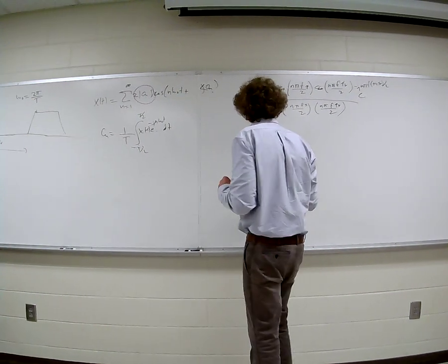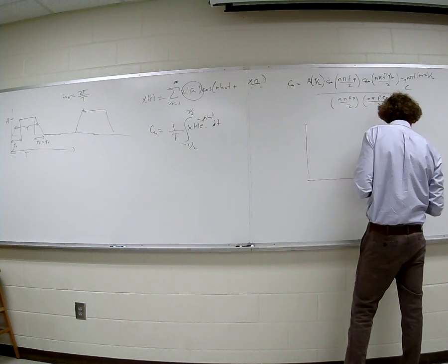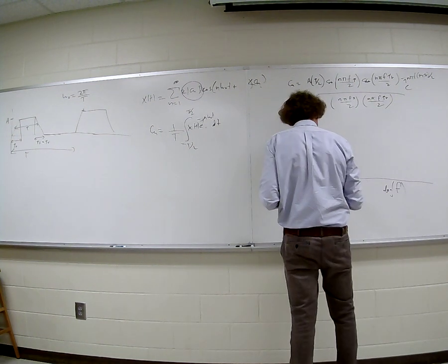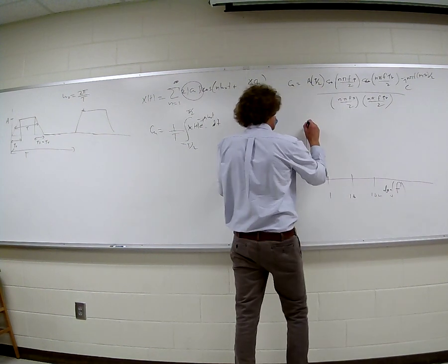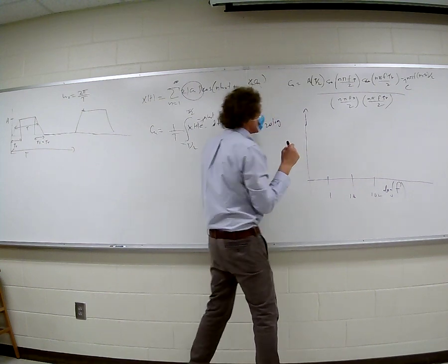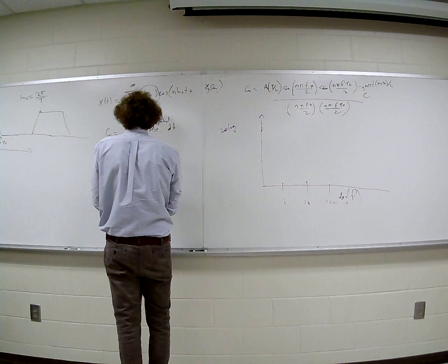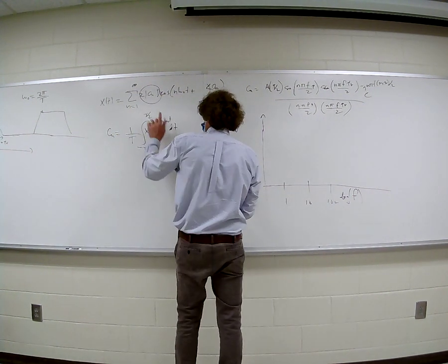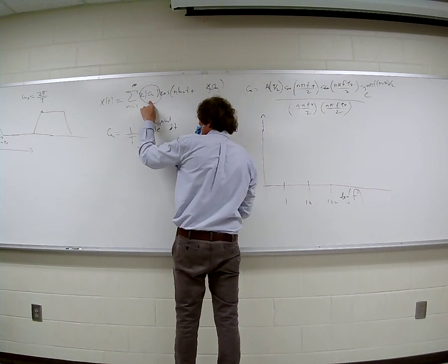If you actually view this versus frequency, I'm going to put it here. This would be f, and this would be a logarithmic x axis, log of f scale, so you basically get 1, 10, 100, and so on. And on this axis, you do 20 times the log. A lot of times they'll take the log of the values of c of n, or 2 c of n, because this is going to be the logarithmic of the coefficients associated with the phasor terms.